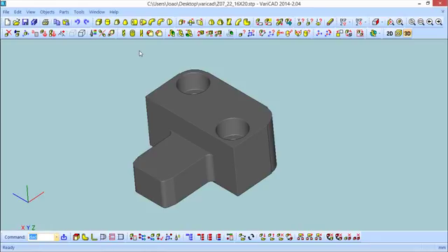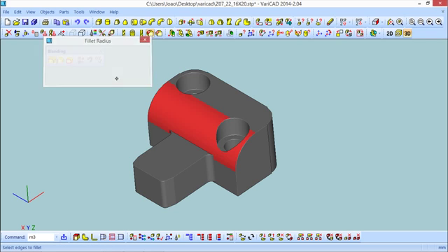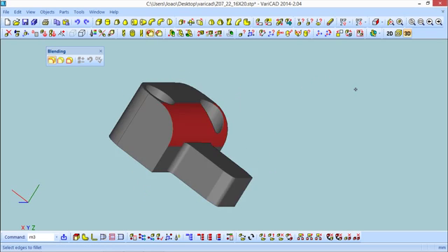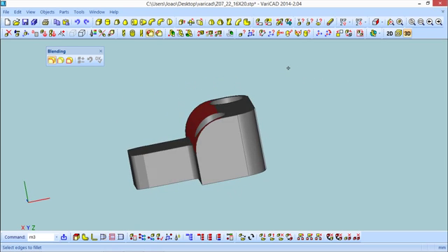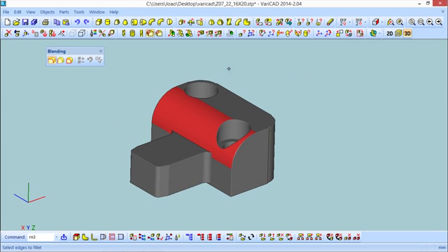One of the specifications, if you can call it that, of a solid is that it is a closed volume, so we can use functions like blendings and Boolean operations. As you can see, if I try to make a blending, a fillet in this case, no problem. Or if I try to calculate the volume, for example,